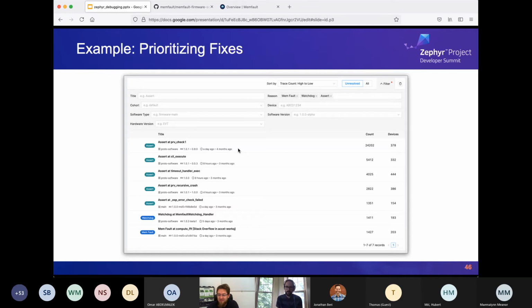Yeah, and it's one of the things where, once you have that remote debugging capability in place, adding some asserts on unexpected code paths is invaluable for fixing issues. I remember I once worked on a project where, when there was a failure with the Bluetooth stack, we would just stop running that task and not reboot the device. But the manifestation of that was that Bluetooth wouldn't work until someone completely reset the device. So adding some asserts to get back into a good state can really help you out there.